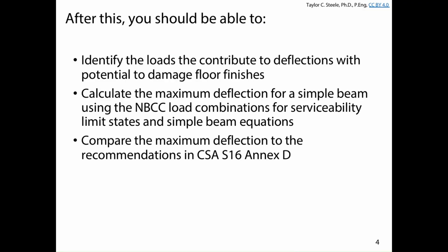Basically, after today, you should be able to identify the loads that contribute to deflections with the potential to damage floor finishes. Pretty much everything we're going to be talking about today is in the context of protecting the stuff that is on the floor from damage under excessive deflection. We've talked about dead, live, and snow loads on structures. Not all of the dead, live, and snow load that contribute to the shear and moment that we designed for will contribute to the deflections that we're trying to limit. Okay, so that's going to be a key for today.